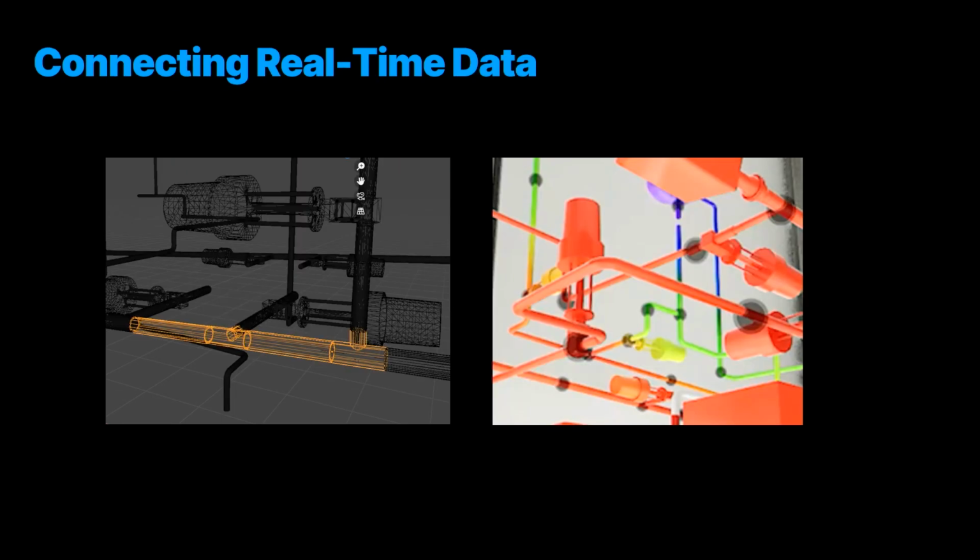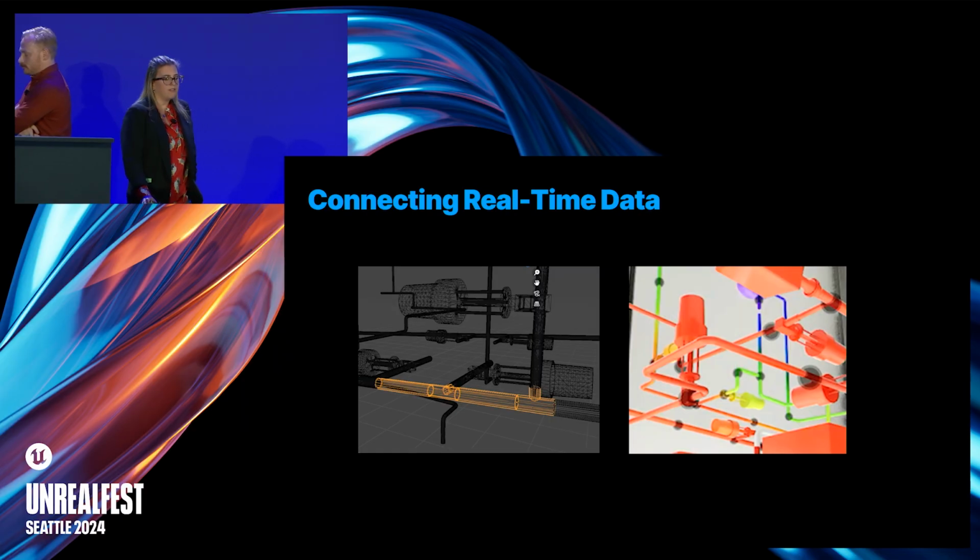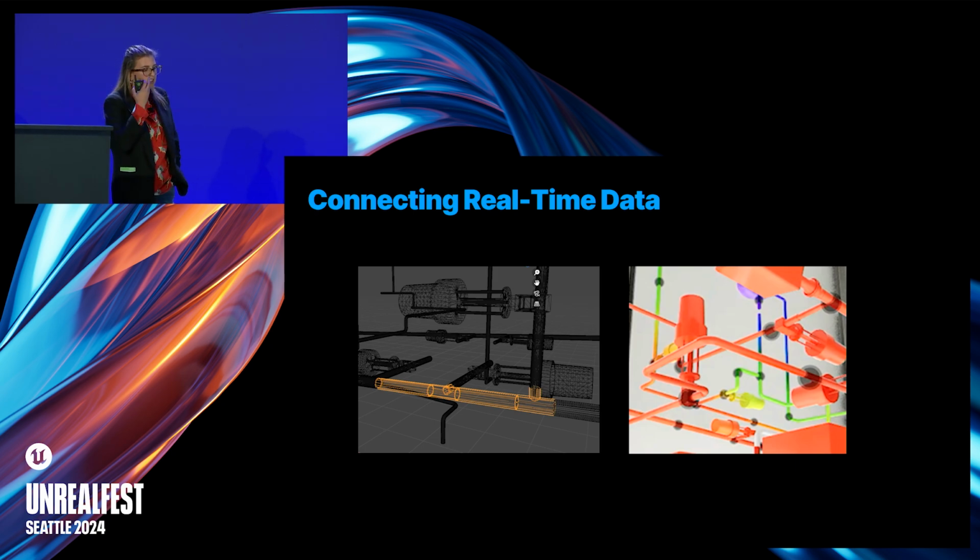All right, once the mesh was broken out across those 220 sensored zones, we began assigning data to each endpoint of the actor, like you're seeing the left and right sides here. You see those little black spheres are the sensor locations. We actually named each actor in Unreal the sensor number so that we didn't get confused across these large quantities of sensors, and we're able to more easily associate the data point with the mesh.